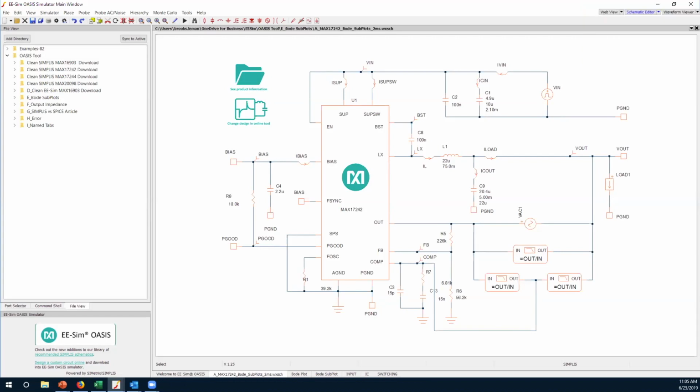Okay, anonymous question. Do the inductor models capture saturation effects? No, we do not capture saturation effects. It is possible to do that, but we do not do that in the models that you can download today. But I can take that question offline on how to implement saturating inductors, because there is a way of using SIMPLIS that allows you to implement piecewise linear models for your inductors and your capacitors. That's above the scope of our discussion.